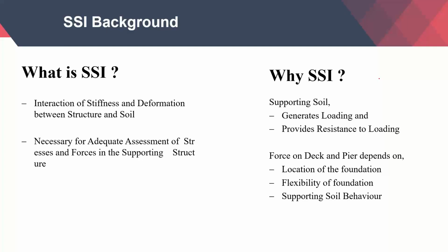So why do you need SSI? Because we also need to check for the supporting soil that generates loading and provides a resistance to loading, because any structural element is only going to transfer the load to the soil. That is why it is very important to check for the soil structure interaction.